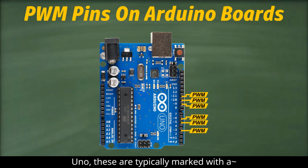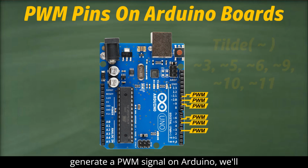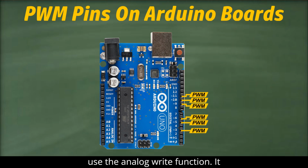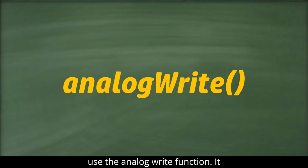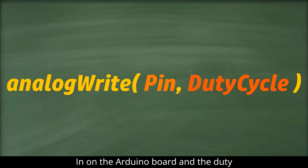On an Arduino Uno, these are typically marked with a tilde next to the pin number. So pins 3, 5, 6, 9, 10, and 11 are PWM pins. To generate a PWM signal on Arduino, we'll use the analogWrite function. It requires 2 parameters, the PWM-capable pin on the Arduino board and the duty cycle value.